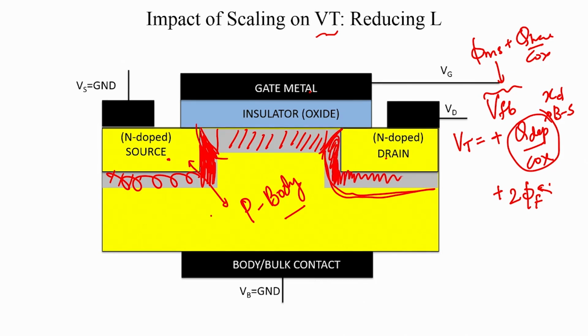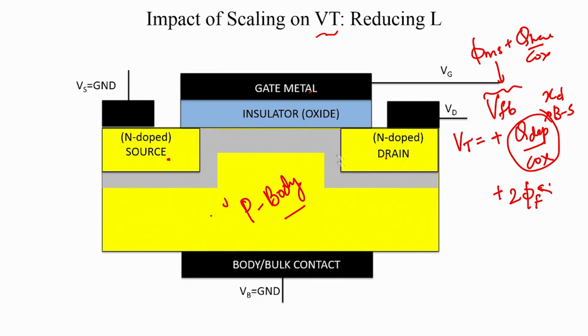In these regions it is only the PN junction, and that region is only the gate, and in this region the PN junction helps the gate deplete. But in a long channel device, let me just write this down neatly. The gate needs to deplete this region.